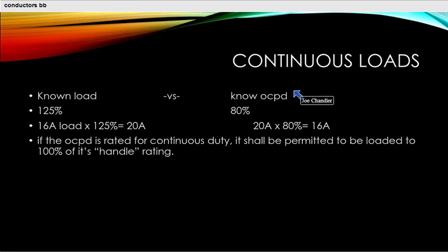So now I'm going to take this 80%, and 80% is the reciprocal of 125. So this is nowhere in the code book. Nowhere does it tell us 80% anywhere. This is just something we did the math on. We know that if I increase this by 25%, I can decrease this by 20%, and look at the number, I get the same thing.